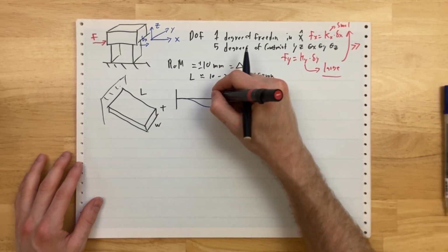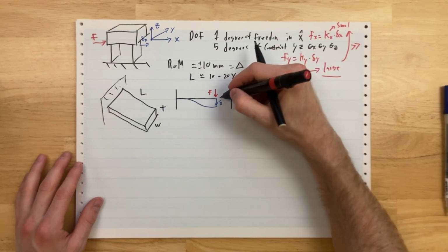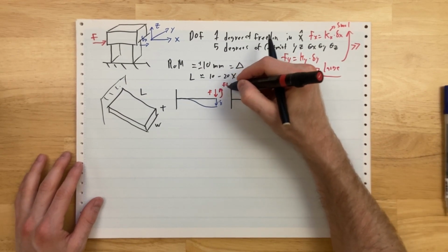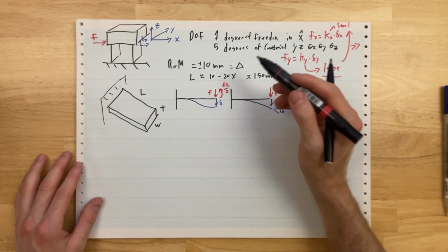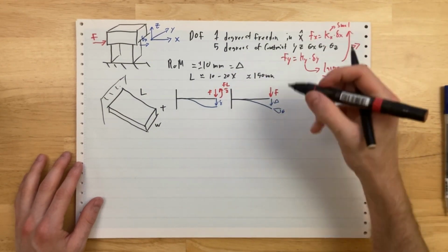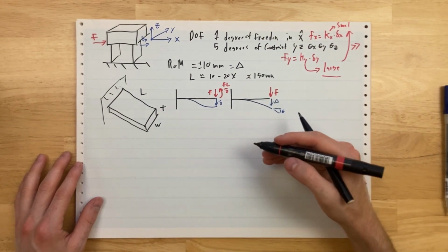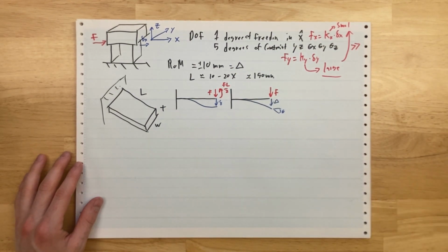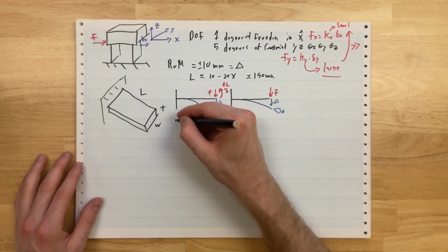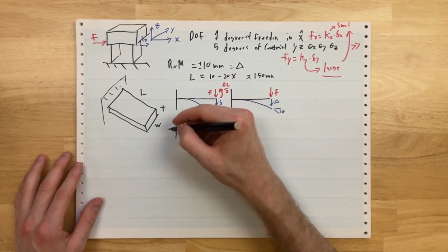If we put in a force F and we put in a torque, FL over 2, we can basically use the torque to bend the beam back up in angular and keep just a pure linear translation output. So what does this look like from a stress analysis standpoint? Let us do the shear and moment diagram.